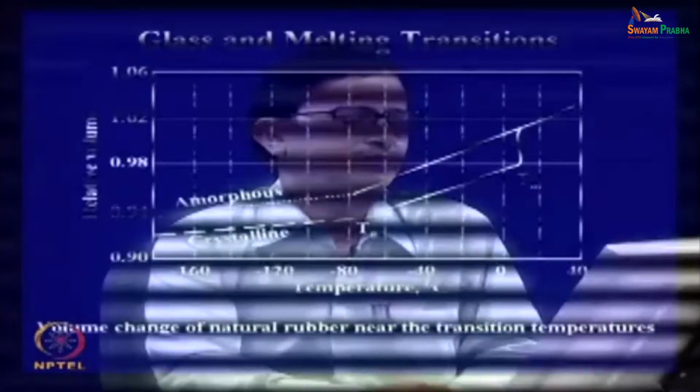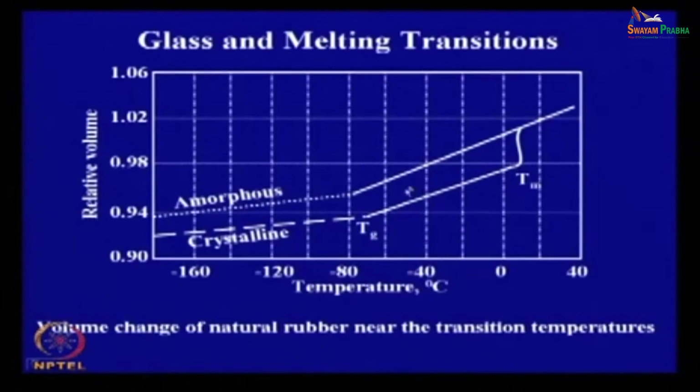And if there is a discontinuity, from the point of discontinuity we can assess a transition temperature, which is known as glass transition, which makes a transition from solid, brittle, glassy state to amorphous, flexible, rubbery state. This occurs due to movement of short segments of polymer chains or segmental movement. This occurs due to onset of segmental movement of polymer chains.